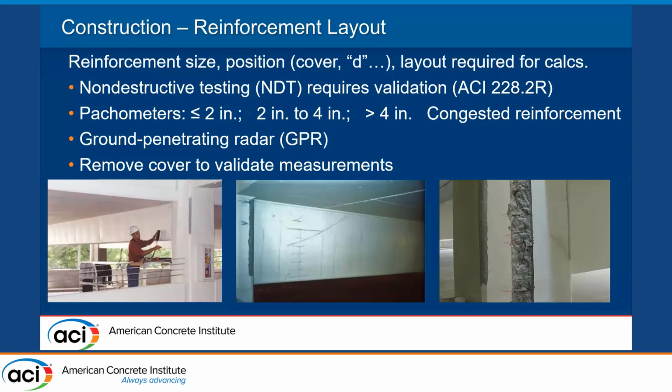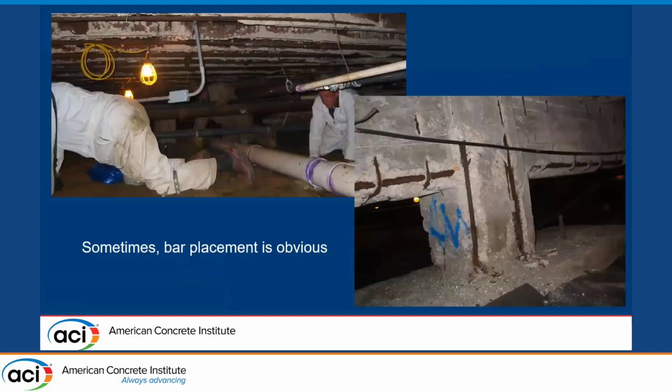The cover was only 1/2 inch, but that's what we determined. And sure enough, we knew why the shear crack was there. And in the beams, there was only about 20% of the shear reinforcement we thought would carry the load. So you use the non-destructive techniques extensively, and check and verify them with physical measurements.